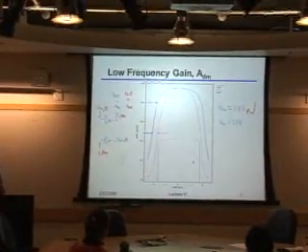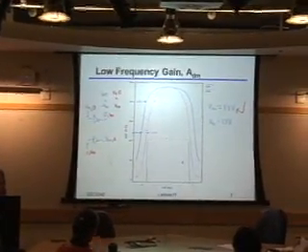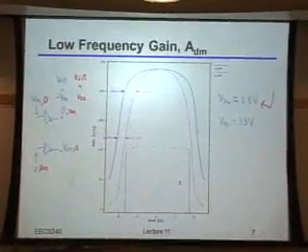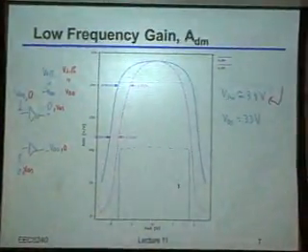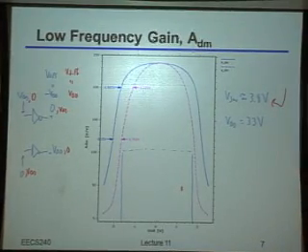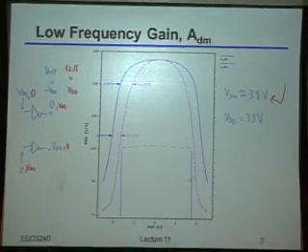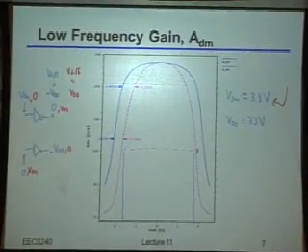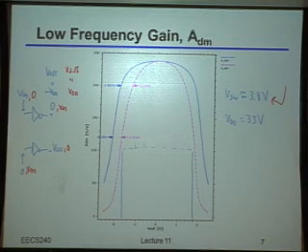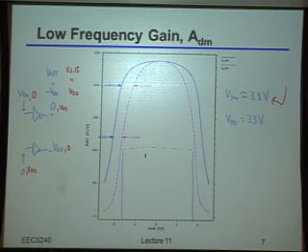So last time we were talking about the folded Cascode OTA. And we started down the path of doing some characterization of the OTA. And I think where we basically ended up was looking at the low frequency gain of the particular structure. So we spent some time talking about how, if you looked at the curve that I've plotted here, which is both small signal and large signal gain versus the output differential voltage, we said that actually the swing was larger than the power supply.